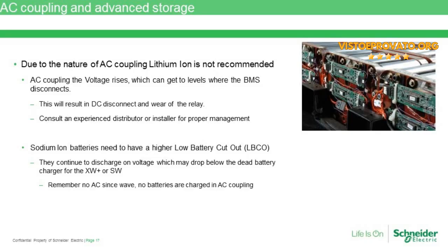But the thing to note with grid tie with battery backup is they're going to be connected to the grid 99.5, 99.6, maybe even higher percentage. Their power outages could just be once or twice a year. And so when sizing those batteries, even if the recommendation is, oh, don't go below 50% depth of discharge, what I'm arguing is that the batteries will actually age out before they cycled out, even if we did a depth of discharge of 100%. Just simply looking at the numbers from manufacturers, typically we can see 3 or 4, maybe 500 cycles out of 100% depth of discharge on a set of batteries.